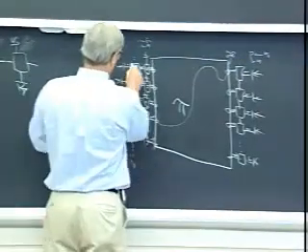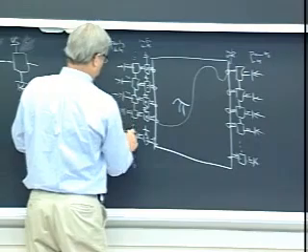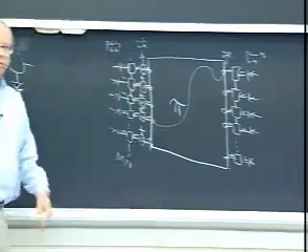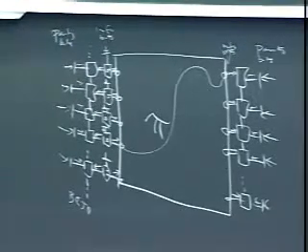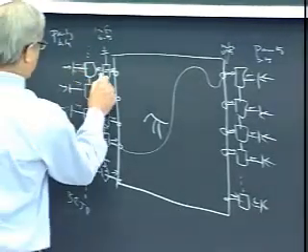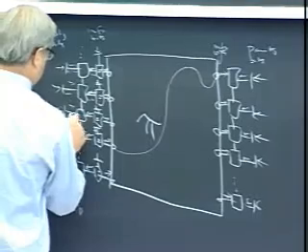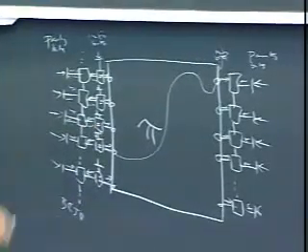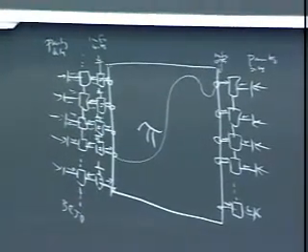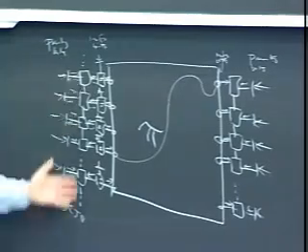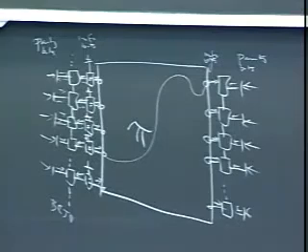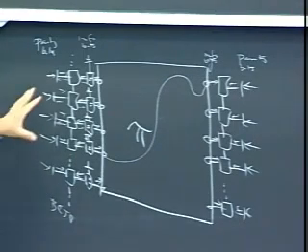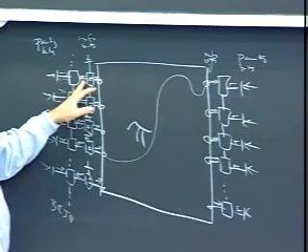Given all these messages, we do our backward-forward algorithm, alphas and betas, eventually epsilons, extrinsic information coming out on all nodes. And that requires going up and down the whole trellis. If this is a 1,000-bit block, as it often is, or larger, it means going from top to bottom through the whole block and doing one sweep of a BCJR algorithm through that block, which will generate a bunch of extrinsic information over here.